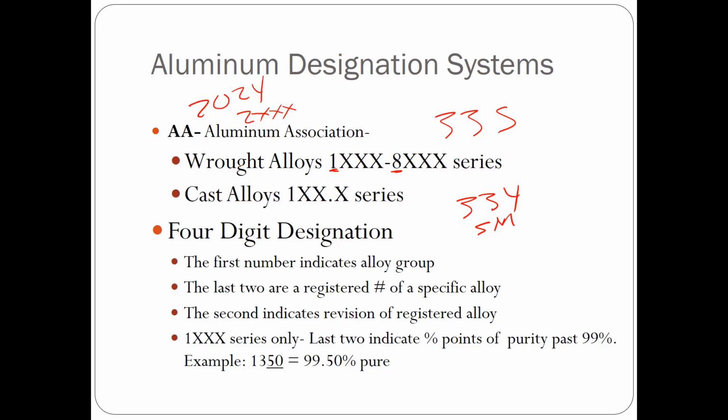So on that spider diagram on the bottom of page 335, at 12 o'clock, we can see that that box, it says aluminum copper, in an upper right hand corner it says pH for precipitation hardening, and then just outside of that it says 2XXX. That's my 2000 series. So this is that box at 12 o'clock.